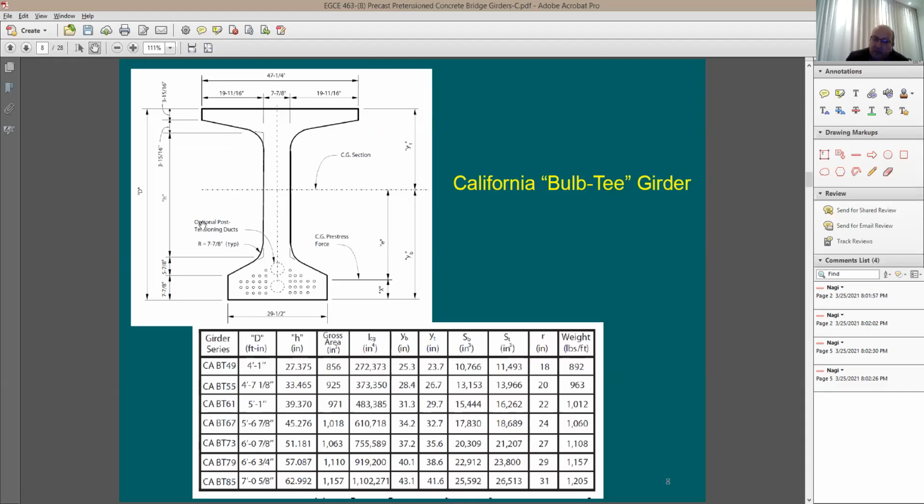And then you can also do post-tension, which means when you buy or fabricate this beam, it's fabricated with pre-tension. So all the small ones are pre-tension, and this has optional post-tension. First you move the beam from its place, rigging it or transporting it to the side of the bridge using these strands for the strength.